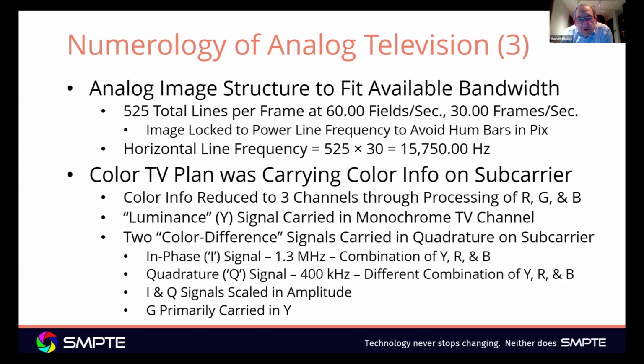red, and then the blue had the narrower bandwidth, primarily because of the human visual system and what was discovered about it back in the 20s and 30s, and advantage was taken of that information to enable better, effectively analog signal compression in developing the NTSC signal. And I didn't mention green, but green, which was the biggest part of the signal energy in the overall luminance signal, was carried essentially in the Y, and only in the negative sense in the I and Q.